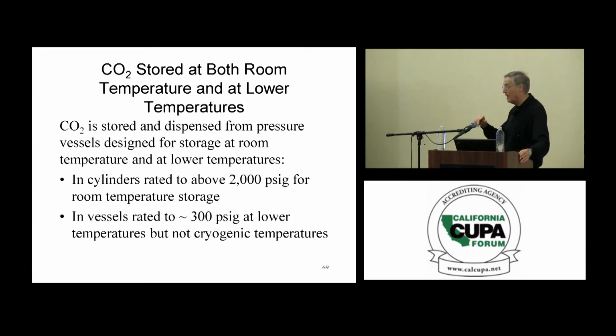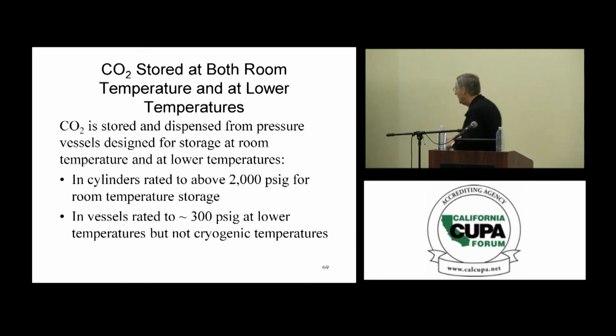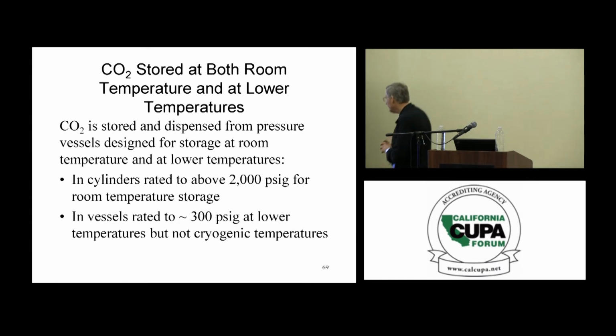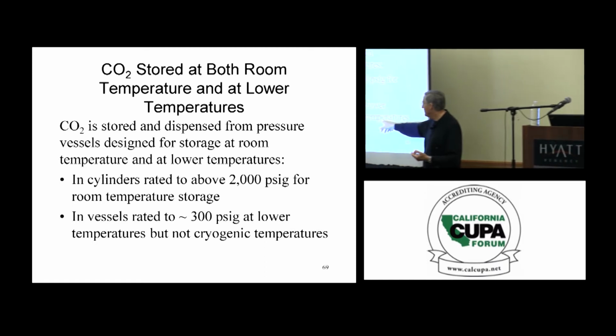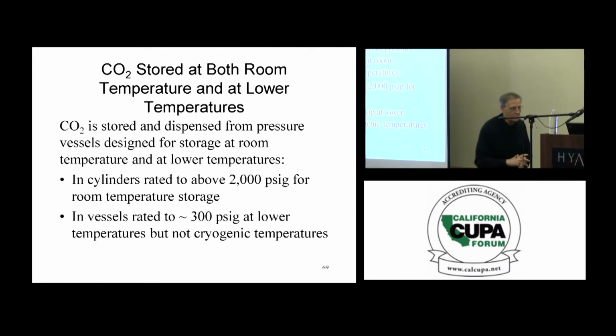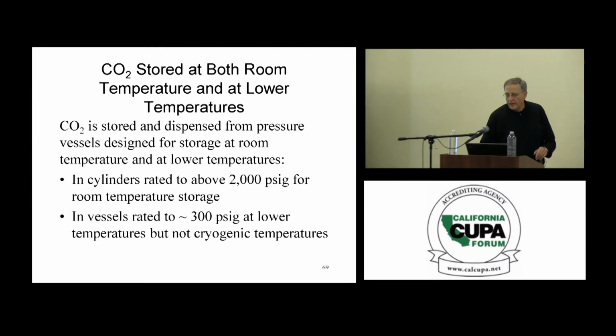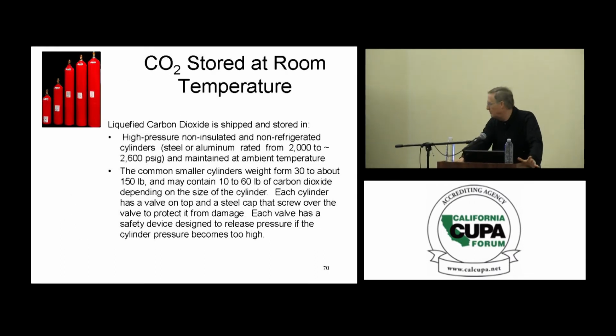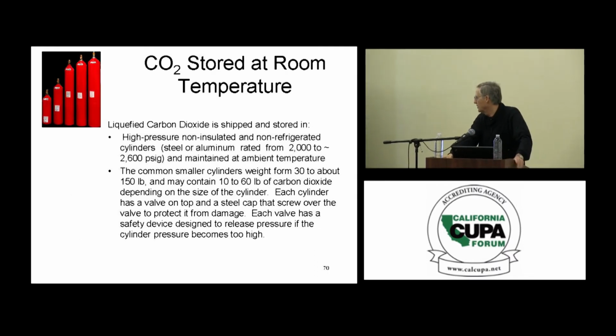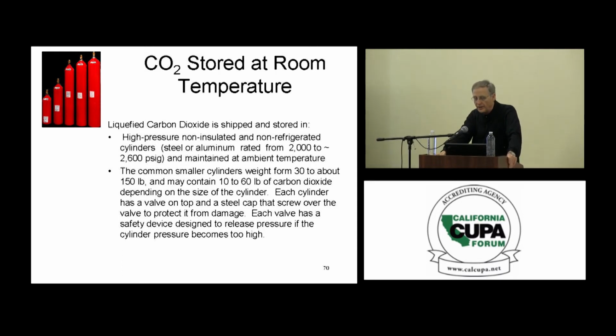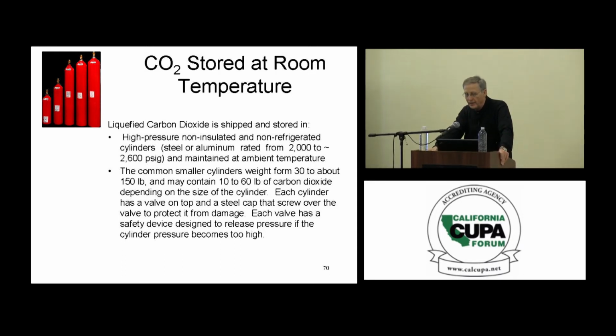There is also CO2 supplied in lower pressure cylinders, but it's not cryogenic. Those are typically supplied at something like minus 10 or so degrees F. And these high-pressure, non-insulated cylinders may go up as high as 2,600 psi. The smaller cylinders will contain anywhere from 30 to 150 pounds of CO2.